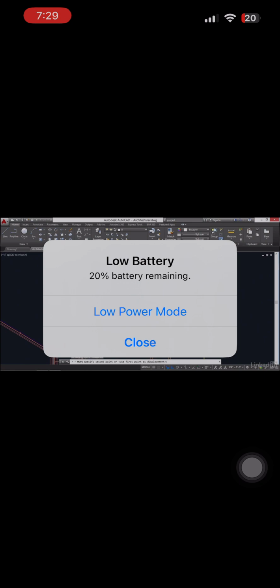I'll hold down the Shift key, right click, and choose midpoint again. Now I'll move the cursor so the midpoint symbol shows up, and I don't have to click it right on there. I could click it over here. As long as that green symbol is illuminated, it will snap it directly to that midpoint. So I'm going to click right now, and that completes the move command. Now let's move this chair up a couple of feet vertically. I'll select it, right click, click an arbitrary base point in this case, turn on ortho by pressing F8, move the chair up. Let's move it up 2'3". I'll type 2'3", enter. So I've restored the lounge chair more or less to its original position.